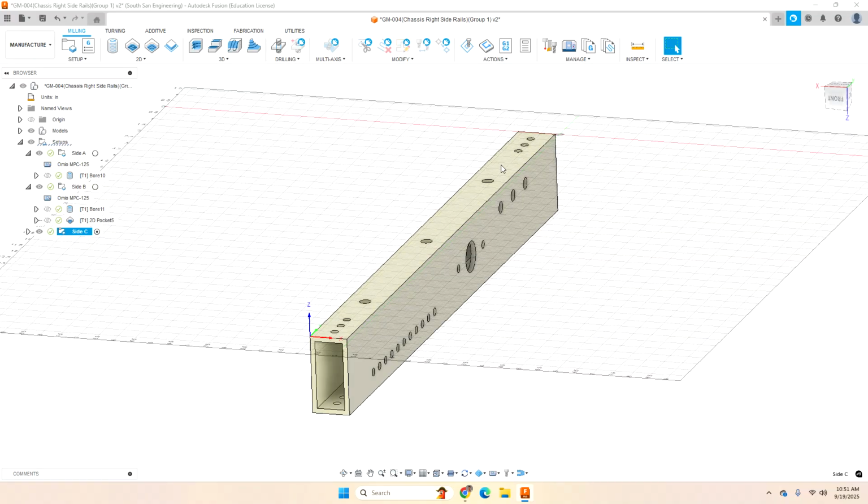These are all, let me check this hole. So I can bore the other ones, but this hole is 0.297, says in the bottom right. So I can bore this hole because it's less than twice the diameter of my end mill. 4 millimeters is about 0.16 inches, so I can bore anything between 0.16 and 0.32, because that'll be 1 end mill to 2 end mill diameters. So I'm just going to go bore all these.